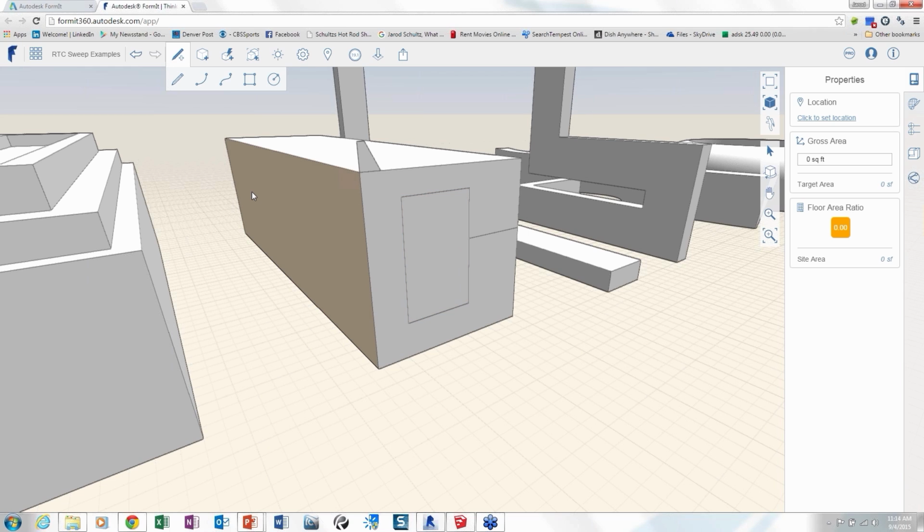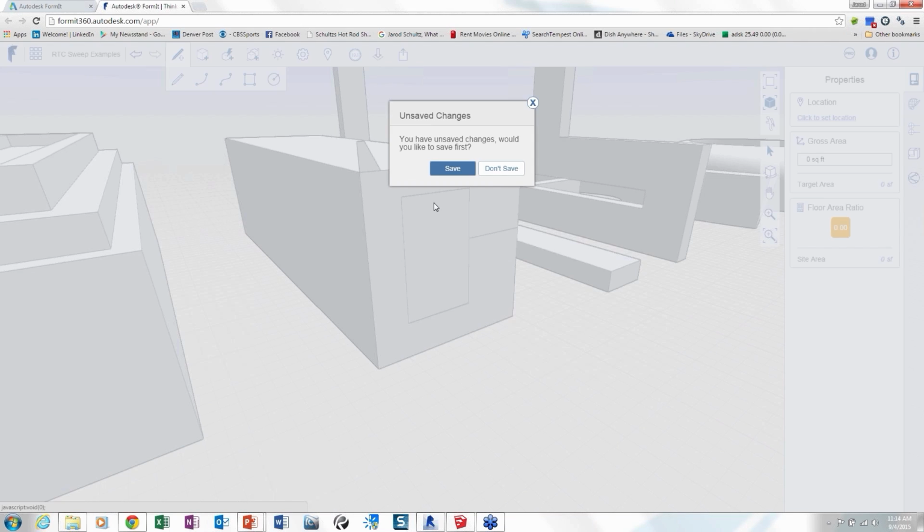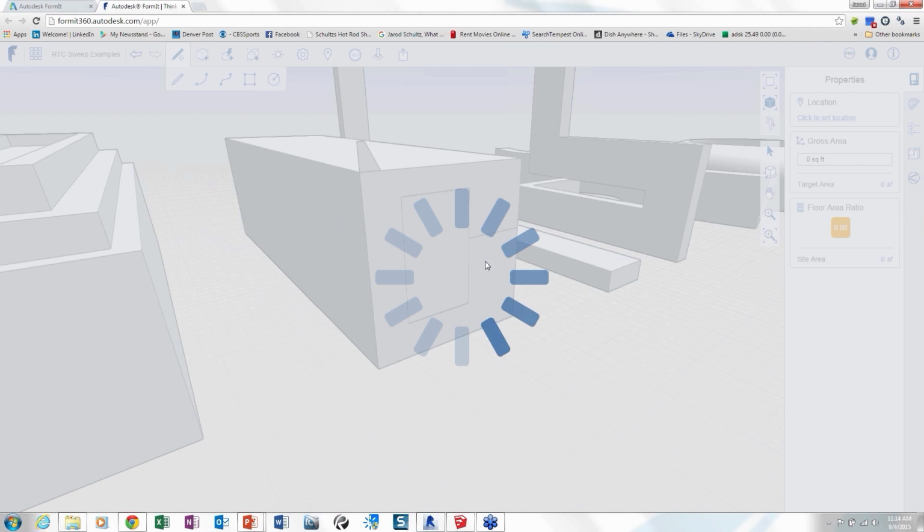Yeah. And I haven't even mentioned roof systems. What I want to do for another example is to start to sketch out your fenestration pattern, like your curtain wall mullion pattern, but not actually put any mullions on it, just the lines. Sure. And then when you go to Revit, you can do just the curtain system. It doesn't even have to be a curtain system. It can just be a curtain panel for each of those, and then you can apply curtain wall mullions onto each of those edges. Yeah, so that would be like this model here that I did.